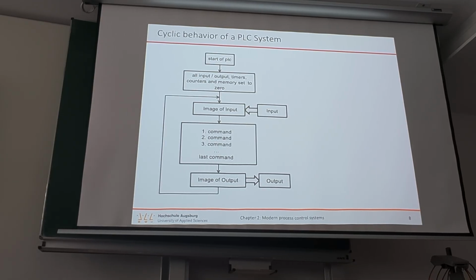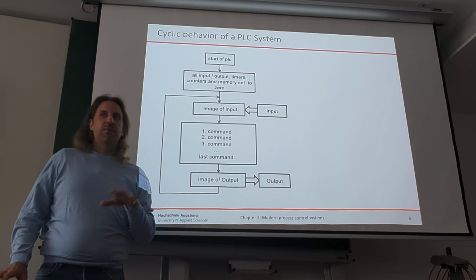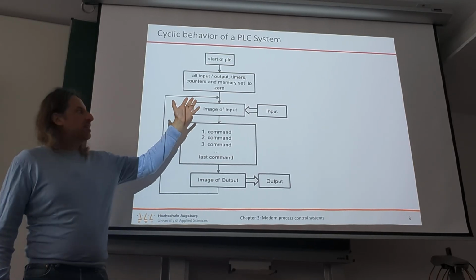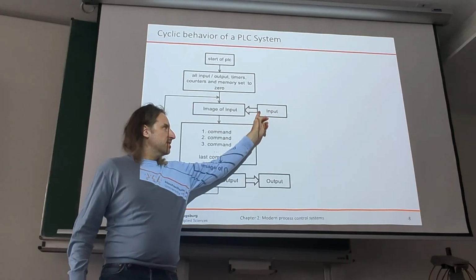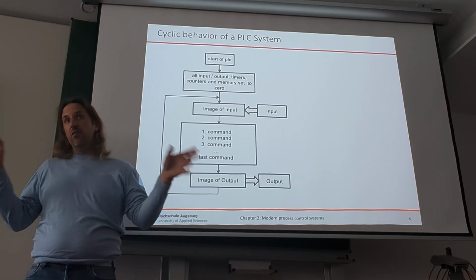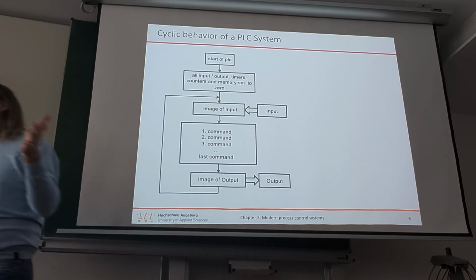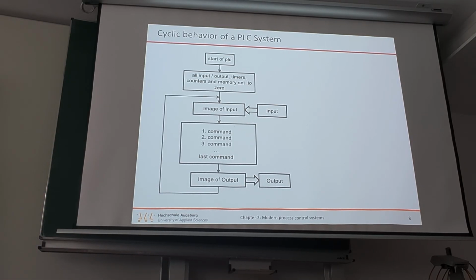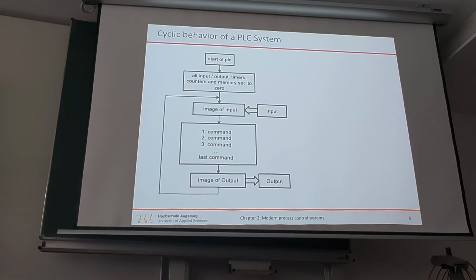You know? Let's say with a very, very slight delay, but it's basically the current value. For control systems, it makes a lot of sense to do it like that, because the inputs might be local inputs, there might be remote inputs, there might be a lot of inputs. Like the big FPSO ships in the oil and gas industry, they have around 300 to 350,000 IOs, and if you just read them in one cycle, that would take time.